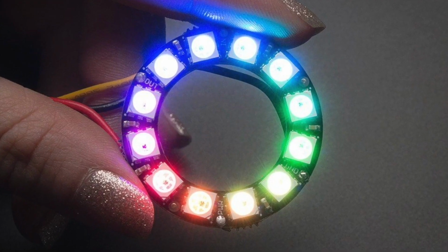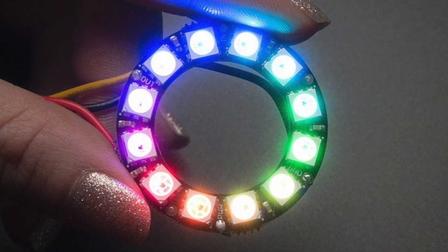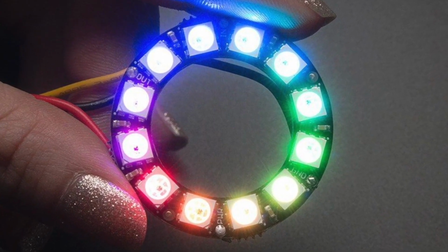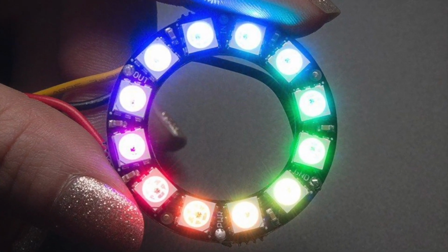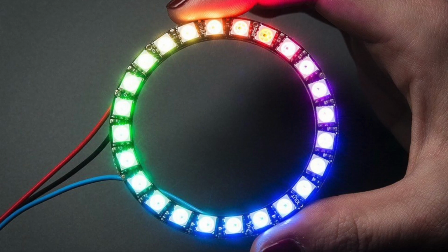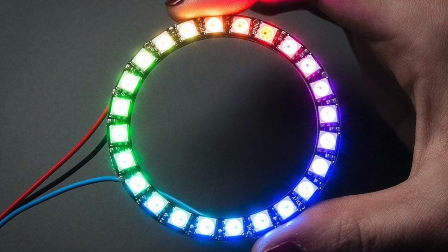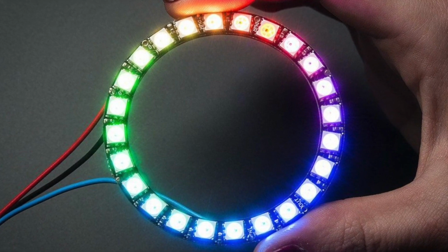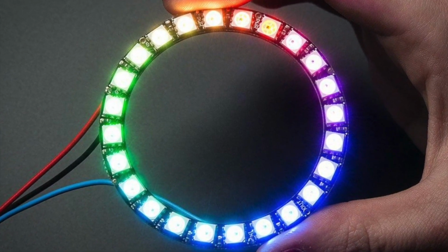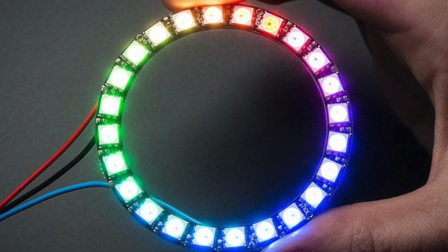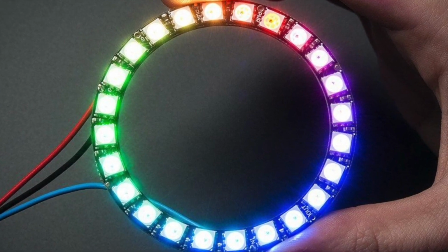LED rings. These come in sizes from about 12 LEDs up to 60. The larger rings require 2 power injections. We'll talk about those later. The smalls can be powered off an Arduino as is. These look cool as they are, but they're also fun to embed inside round objects. They can make cool eyes if you install them in pairs and are careful with the programming.